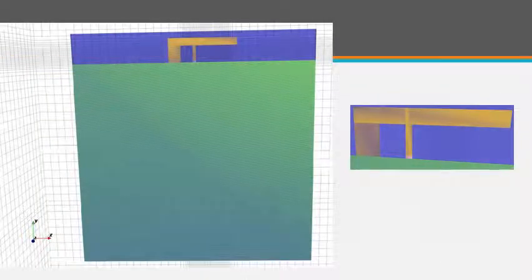So here we have an inverted F antenna simulation in MATLAB using OpenEMS. As you can see, the ground plate is a really large plate in the bottom half, and we have what is an inverted F on the top half, which creates the radiation. We also have a zoomed in version on the right hand side, as you can see.